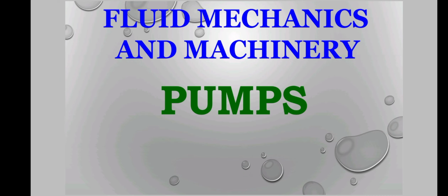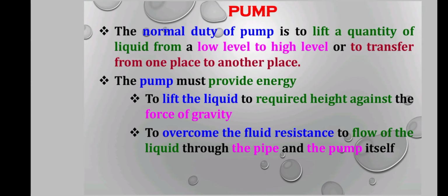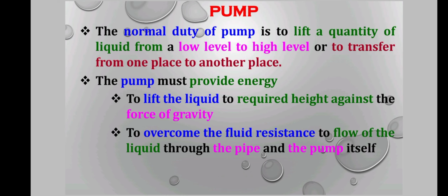So our topic is pumps. The normal duty of a pump is to lift a quantity of liquid from a low level to a high level, or to transfer it from one place to another. The pump must provide energy to lift the liquid to the required height against the force of gravity, and to overcome the fluid resistance to the flow of the liquid through the pipe and the pump itself.